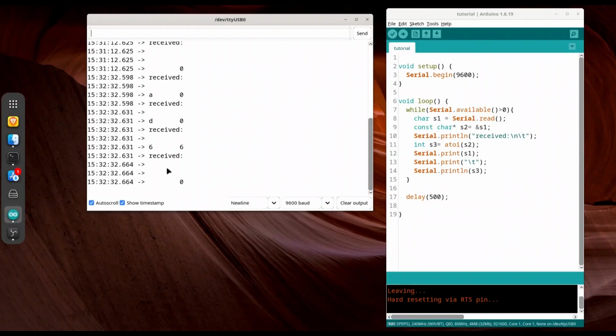So this is the way to receive only one character through our communication channel. Now I'm going to show you how to use the function readBytes. And this is actually a function that you are going to use in most cases. For example, if you have multiple microcontrollers that are going to access some server for instructions or some other data, the best way to communicate is through reading and writing bytes. And let me show you how to do that.